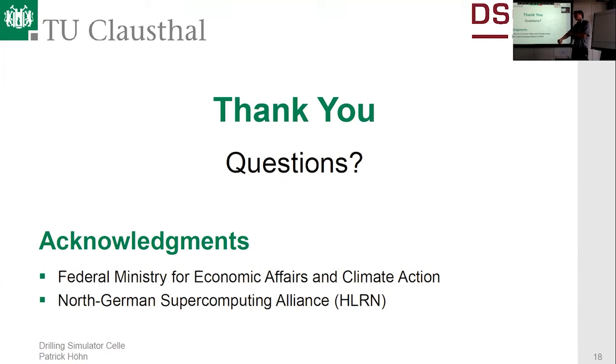Okay. And then how big are your particles? And they have a lot of mass, so is there a strong impact of particles on the structures? I would expect, if they are just immersed in the fluid, probably not. But I would expect a larger impact if you have a particle bed, which basically was in all my experiments. If I had particles in the experiments, I had a particle bed because I could not run the flow loop as fast as I wanted to really have them immersed in the flow. And that's also, I would say, the most crucial part when you look at the application in the drilling industry.